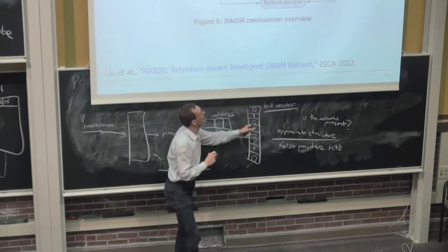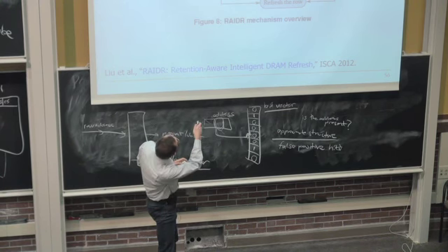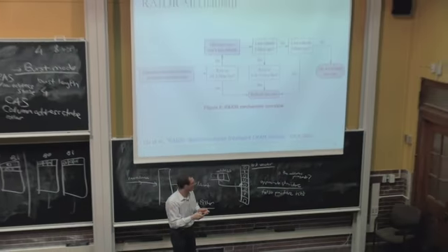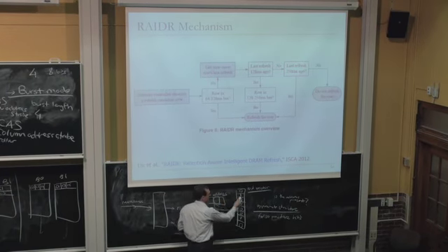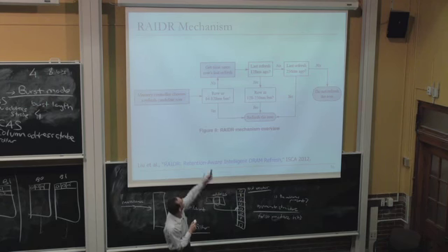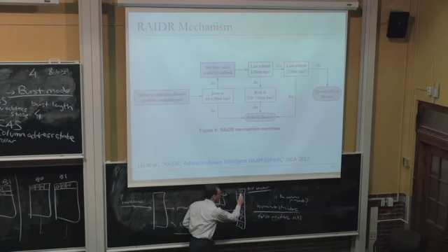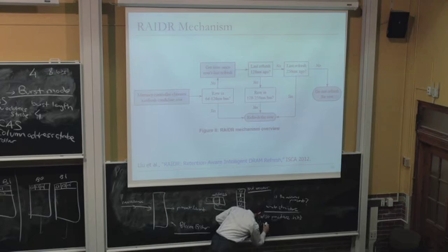So this Bloom filter can tell you this row actually has a retention time between 64 to 128 milliseconds, whereas it doesn't. Because it just so happened that some other row that had the same bits mapped to the same address had a retention time of 64 to 128 milliseconds, and you had to set the bit because you want to refresh that row. Okay. So that's the concept of aliasing in the Bloom filter. That's why you get these false positives.